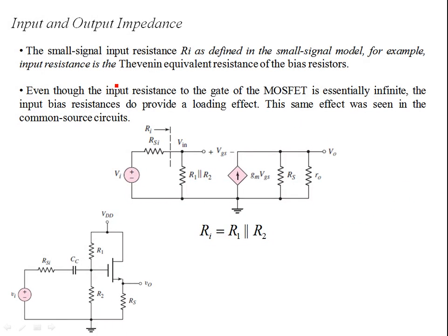In part 43 of this lecture series on MOSFETs, we derived the small signal model, including the AC equivalent circuit of a common drain circuit, or the source follower. Over here you see this is the gate terminal, the drain is common, it's a source follower circuit, and this is the source. The difference over here is the VGS, the potential difference between the gate terminal and the source terminal.